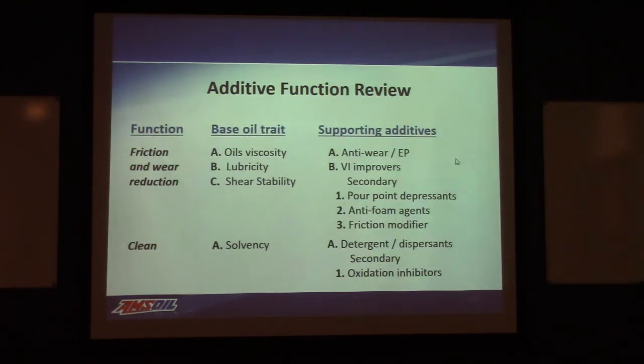But from a supporting standpoint, any anti-wear or EP additives are going to address friction and wear. VI improvers. Why VI improvers? Because they're going to maintain the viscosity at higher temperatures. Maintaining the viscosity, higher viscosity, better wear protection, and so on. You understand where I'm going on here.